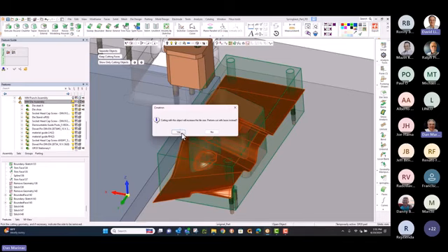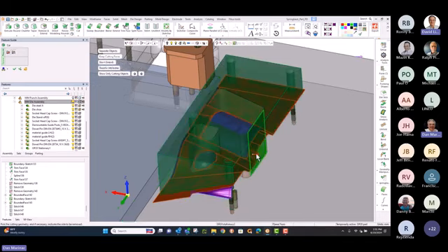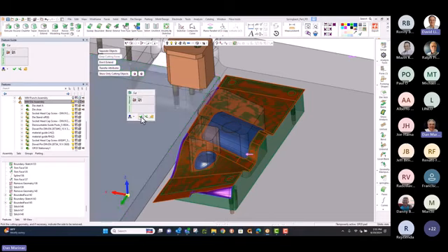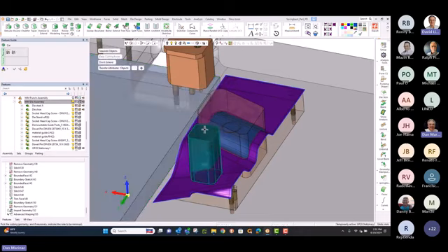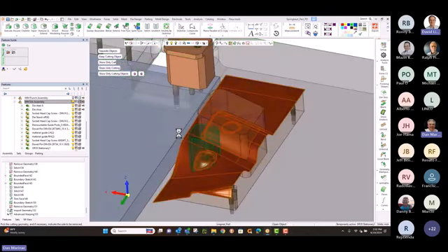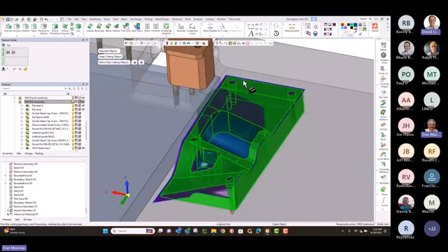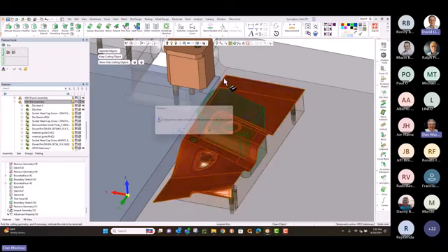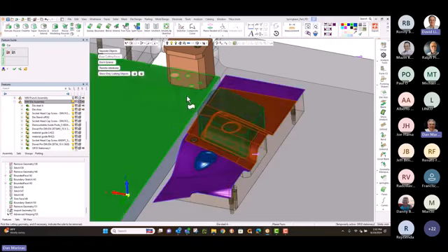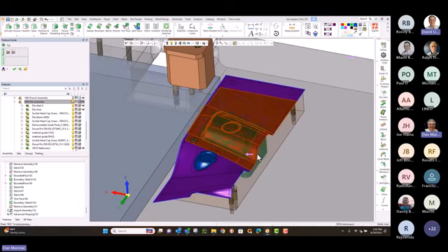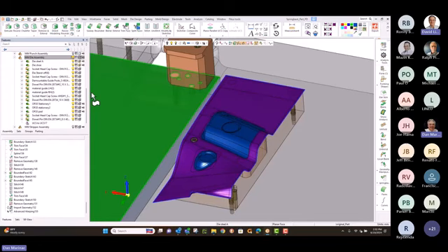Basically now I'm taking the form and I'm using that cut sheet to cut back the block I drew. And I'll do that with other forms here just so you get the example of what it would look like with inserts, maybe some retainers around it, things like that. You notice too that there are different types of components, screws and dowels. All that comes with the system. It's got an extensive library of different die components that you would use. Once you place it, it automatically places the hole, keeps track of how many times you've used it, so on. So here you can see very quickly we can just simply cut it back, and we'll have the die forms that match the compensation that we need.